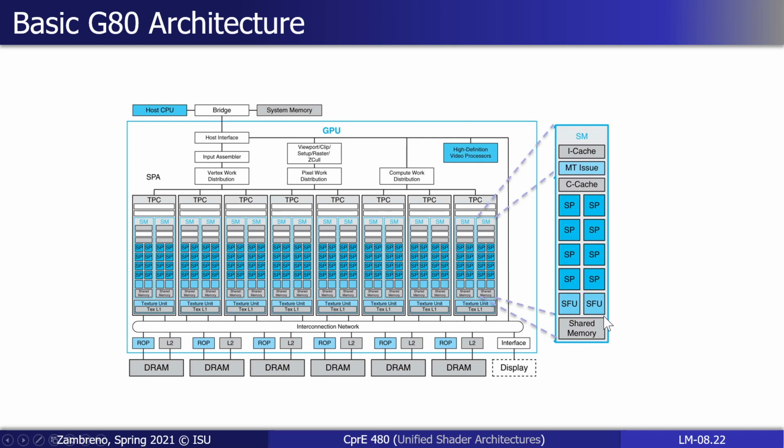One takeaway from that is that those special function units, let's say sine of x, to calculate that, should be faster, presumably, than a software lookup table or other algorithmic approach to calculating trigonometric functions. But it's not free, in the sense that addition is effectively free in our SPs here. There are fewer of them on the core. They presumably then have some scheduling associated with them. We've seen a little bit of that with our divider core. Dividers are significantly more expensive in terms of transistor budget than adders, as well as multipliers.